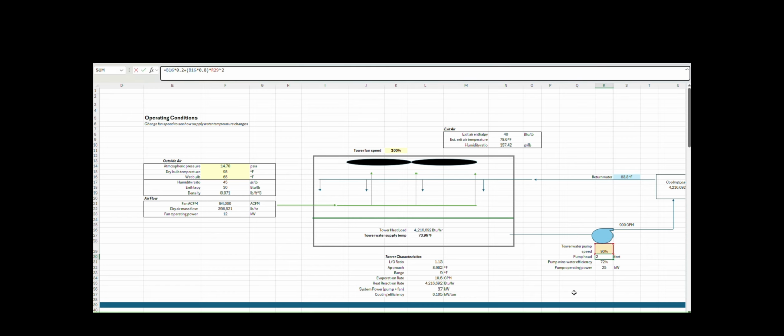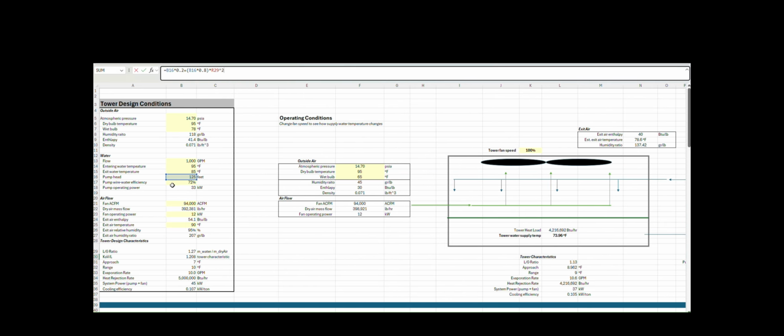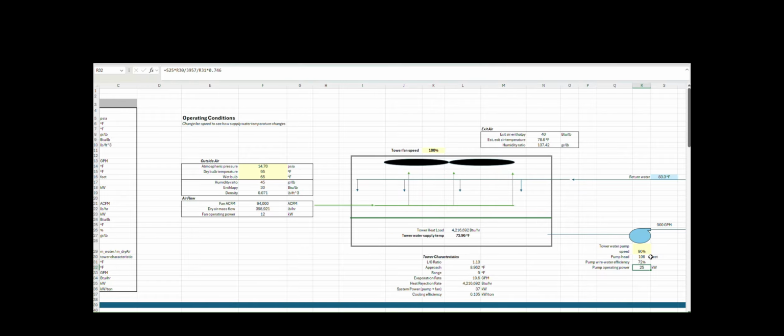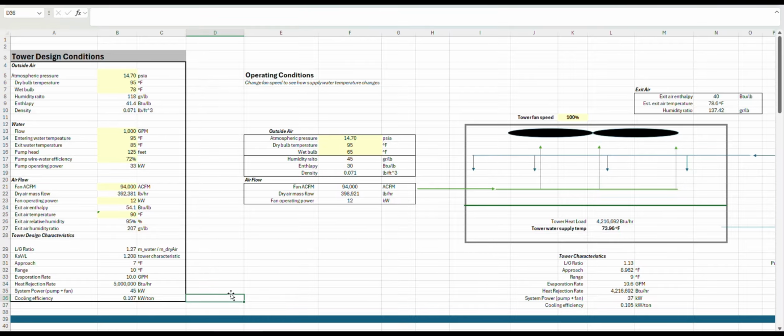To be more conservative, this is assuming that this 125 feet is 20% due to static head, which is not going to change ever, and then the other 80% is due to dynamic friction losses. I find that's a little bit more realistic than just doing a straight up affinity law calc. I hope that helps, and good luck.